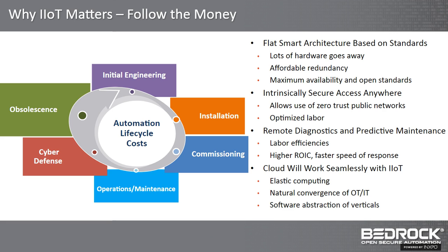There are many smart, cool things to do here, where by moving in this direction, you unleash a bottleneck of data that's sitting out there on the edge. In many cases, it is a 20-year-old HART DP cell from Rosemount that's just loaded with diagnostics and secondary measurements, or a smart motor control on Profinet that's just begging to be called to the internet in a secure way so you can understand what's going on with that motor.